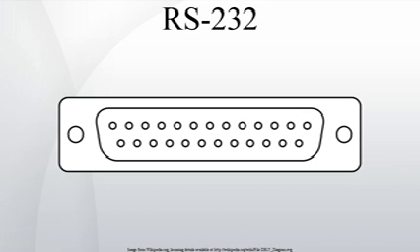Conventions. For functional communication through a serial port interface, conventions of bit rate, character framing, communications protocol, character encoding, data compression, and error detection, not defined in RS-232, must be agreed to by both sending and receiving equipment. For example, consider the serial ports of the original IBM PC.